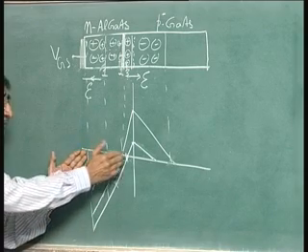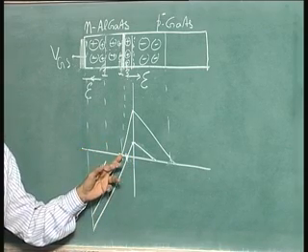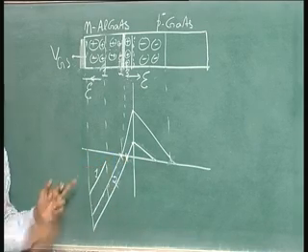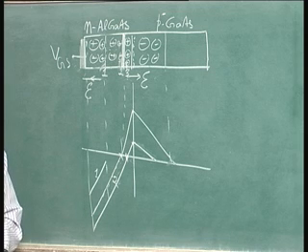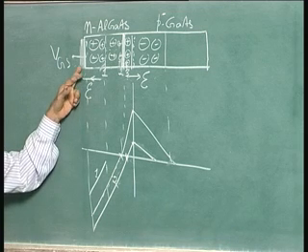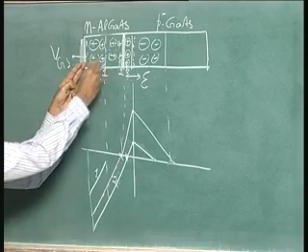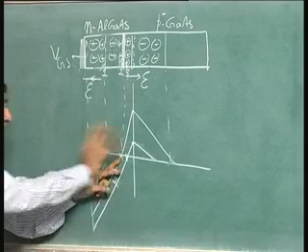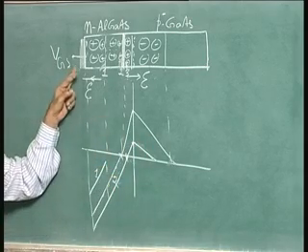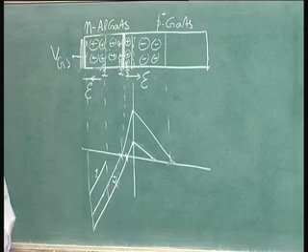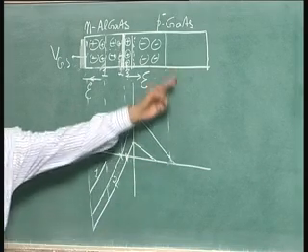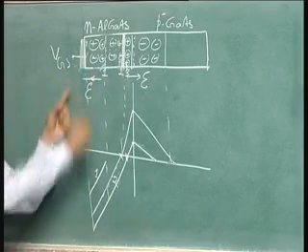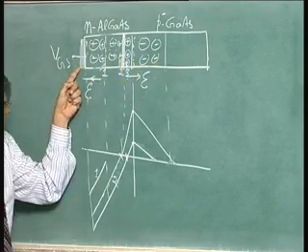What we have seen now is this is getting pushed in this side, telling that the minimum point or 0 potential, the 0 electric field point has shifted to the right, or the minimum potential point has shifted down to the right. But actually what happens is, when you put minus charges here, if the whole thing is depleted at this point, if I put a minus charge here extra, that is if I increase VGS, where will the plus charge come from? From the other end, because it is as if there is an insulating layer.